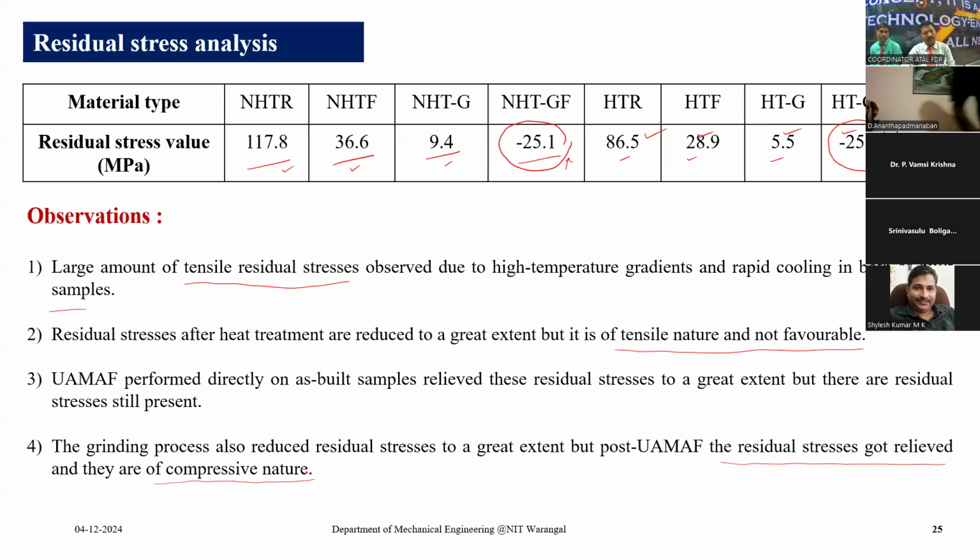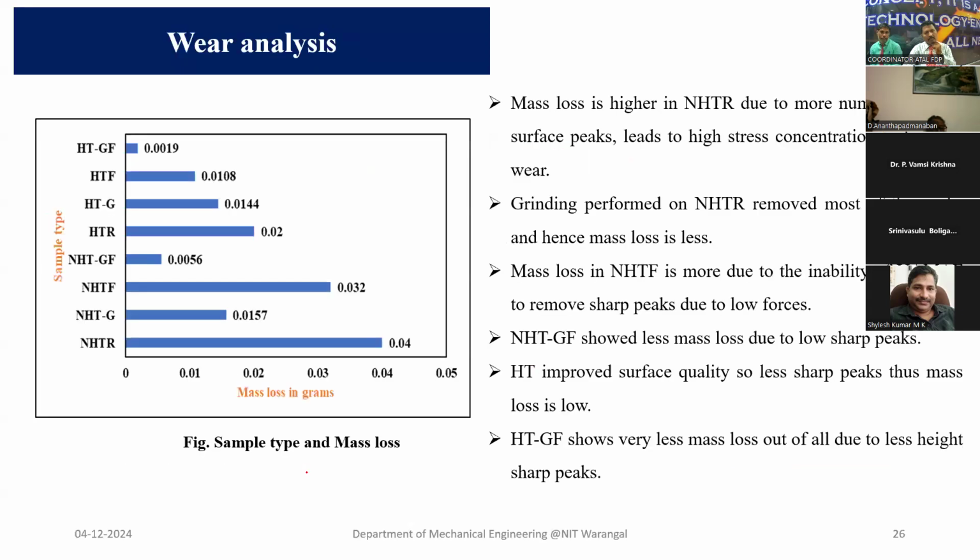Of course, we took only rectangular flat components, but for components with any complex shapes, the fatigue life is very important because stress concentration will be there on the peak corners, so the fatigue life is very important. So this is also wear analysis.